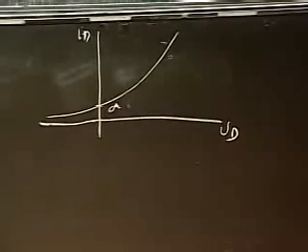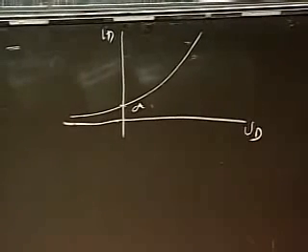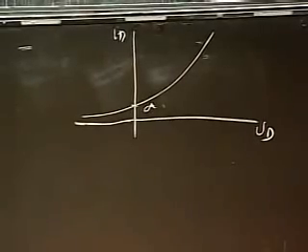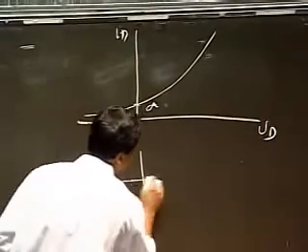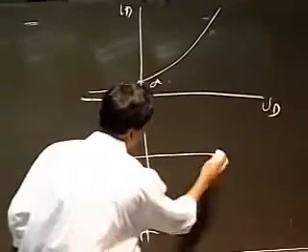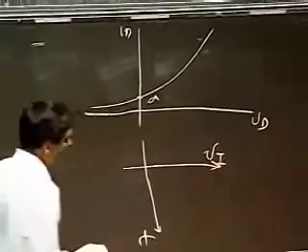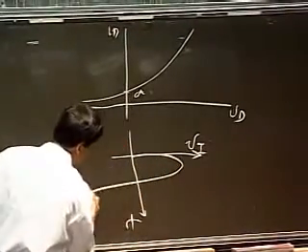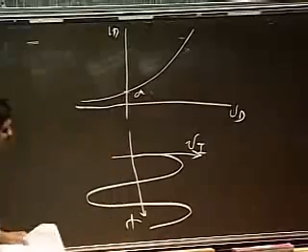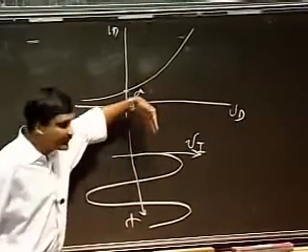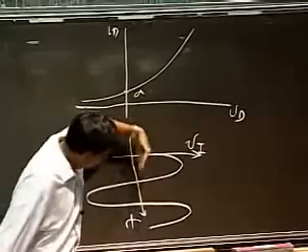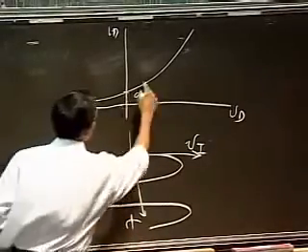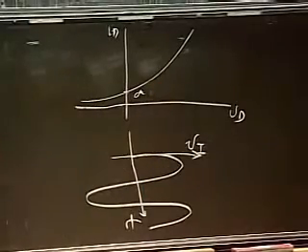Okay, and what I'm going to plot for you is if I have a time-varying VD voltage, I just want to see what the time-varying ID current looks like. And a trick to plot that is to take your input voltage like so. And let's say I apply a sinusoid. So I'm just taking a time-varying sinusoidal voltage and plotting it, just rotating the plot 90 degrees like so.